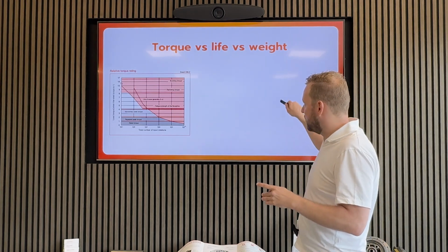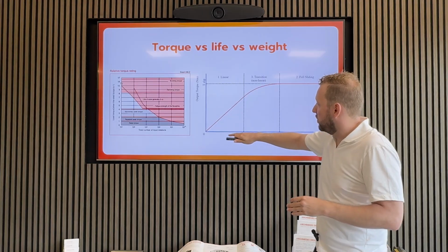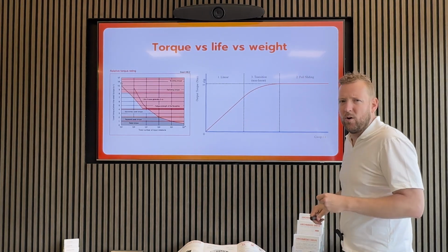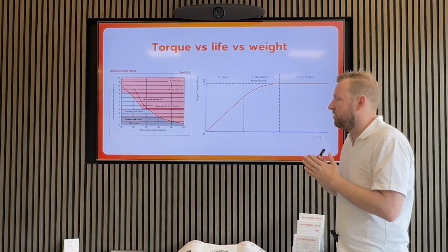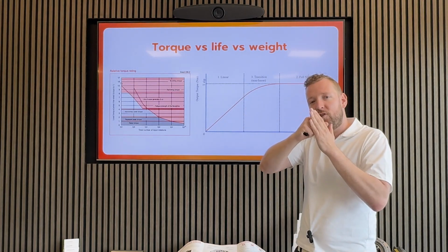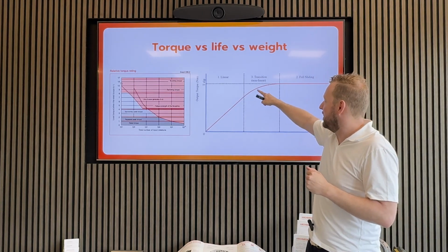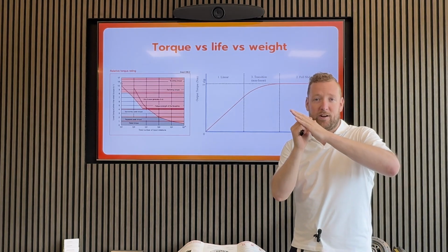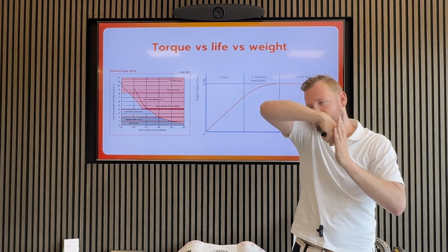But you have to see the bigger picture, and that is that typically, if the torque increases, there's a factor called creep in our drives, and that relates to micro slip. And there's a linear region where everything just sticks and rolls, and a full sliding region. And in between that, you have the transition where there's so-called stick-slip behavior, and it slips and sticks, slips and sticks.